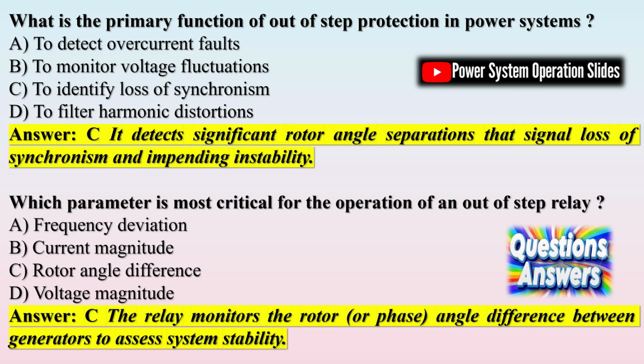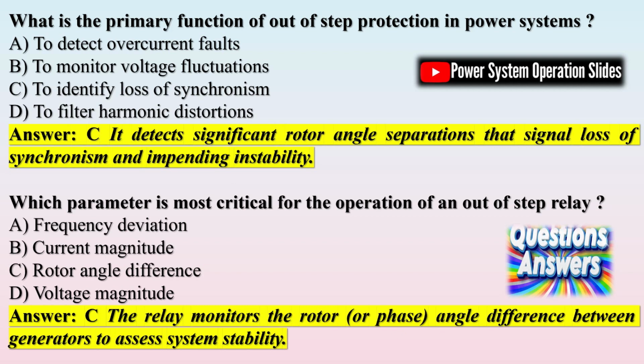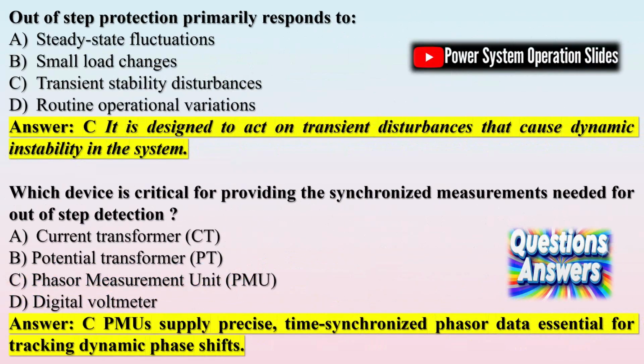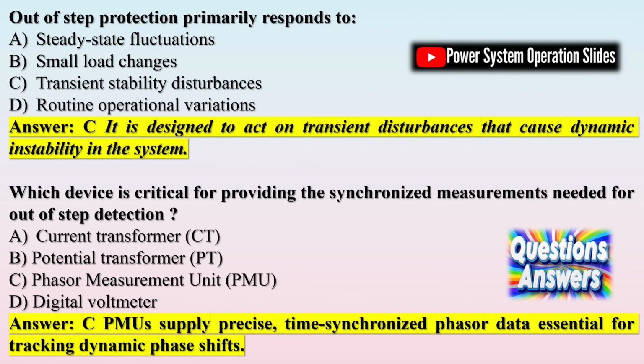Distance protection for faults during system out-of-step. Even while a system is in a power swing or an incipient loss of synchronism state, faults, e.g., short circuits, may occur. Designing distance protection for this scenario requires careful consideration. Correct fault detection: the relay logic must differentiate between the impedance variations caused by a fault and those stemming from a power swing. Unblocking mechanisms.